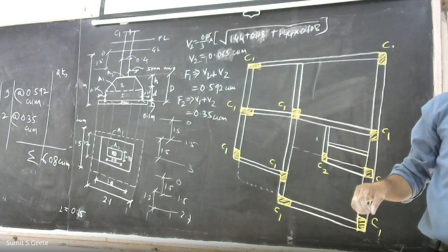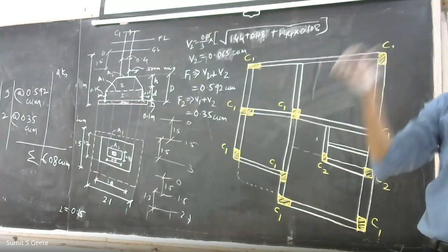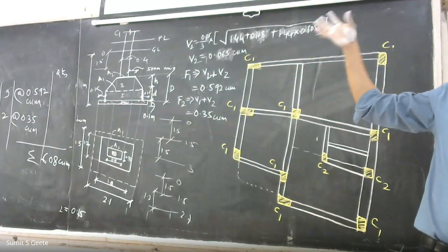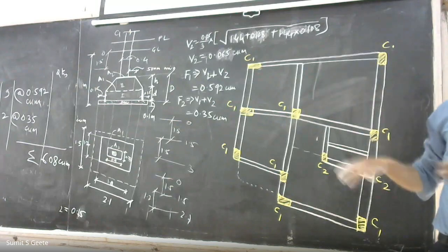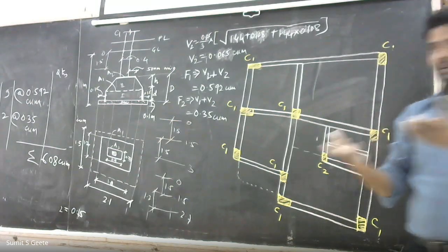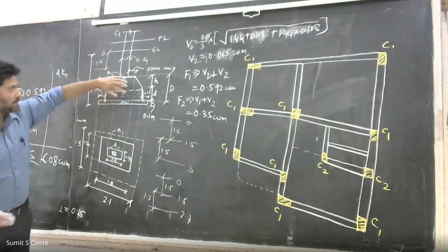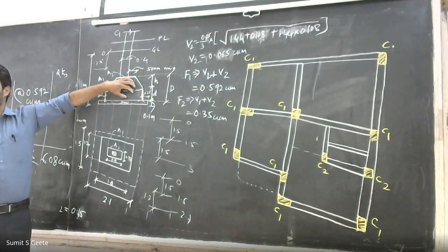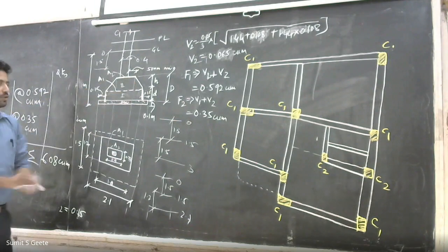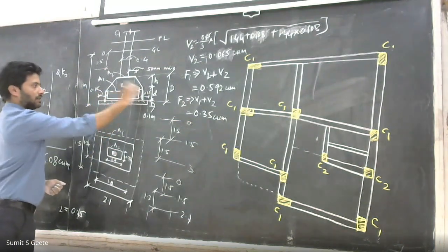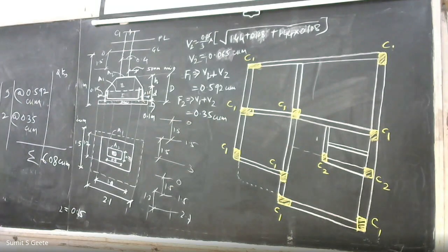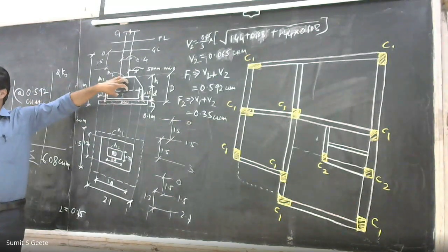Clear? Secondly, how is the reinforcement cage going to be considered or laid down over here? How will the reinforcement cage be? In case of this particular part, there is no reinforcement. We are providing the reinforcement at this part only, in the form of mesh. Okay? We cannot provide anything else. So here there is only concrete. So what should be the value of slump?